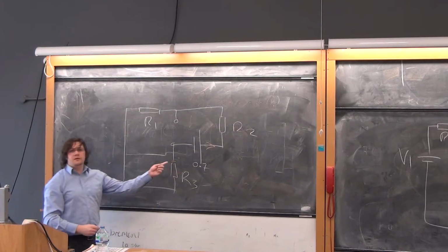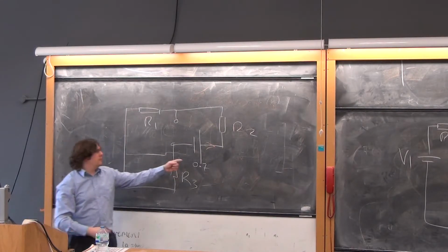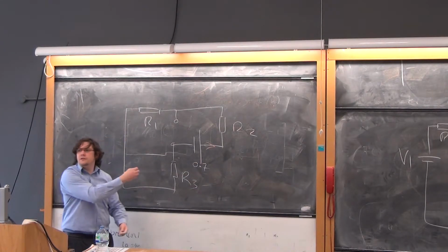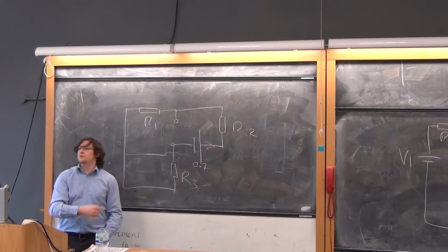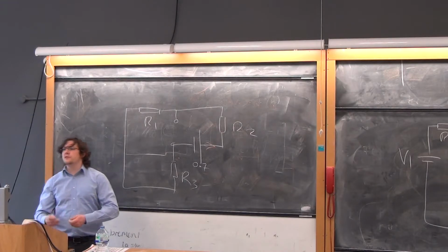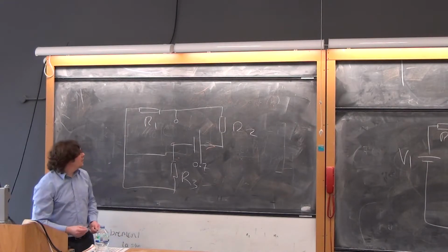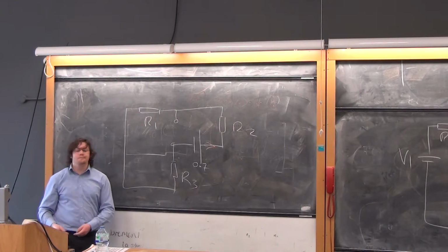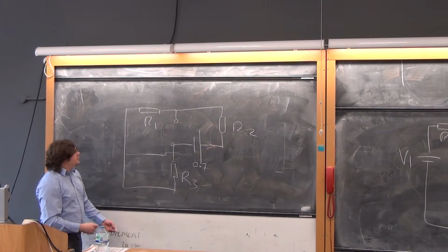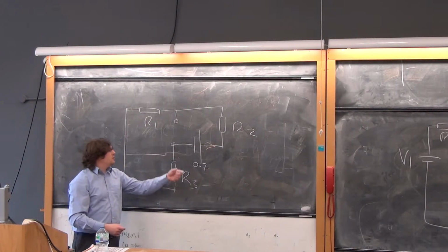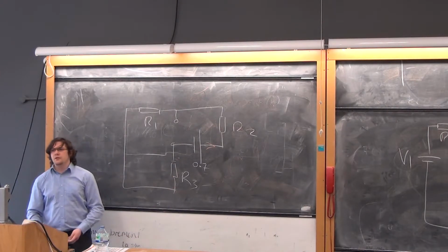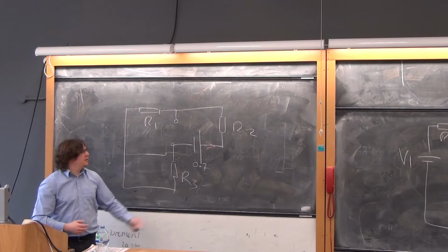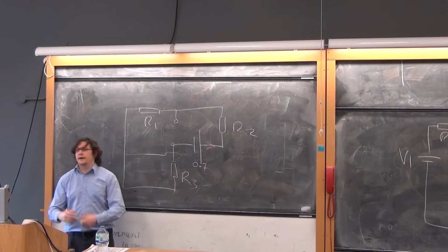And that's why the direction of the current is important. In the very first circuit I had, we drew the current the other way. And we'd have to make sure that we subtracted this one from the first one, or subtracted the first one from this one, depending on how you want to write your equations out. One way or the other, they can't both be added. So we do R3 plus R1 plus R2, 0.7 divided by that lot, gives you the current. And then you'd, taking the signs into account based on the directions of your arrows, add them all up.